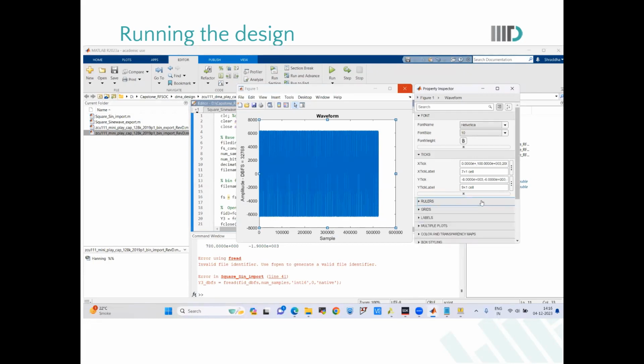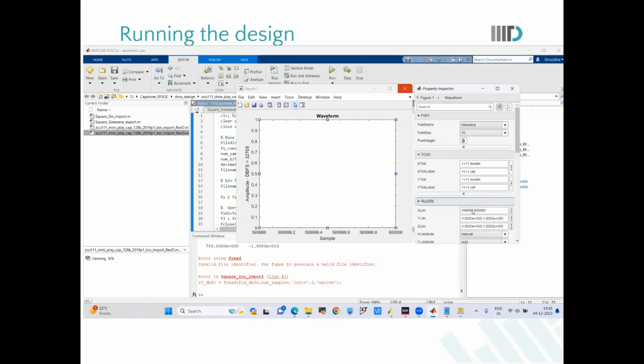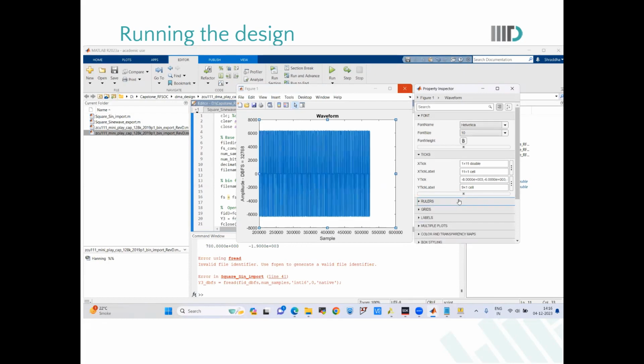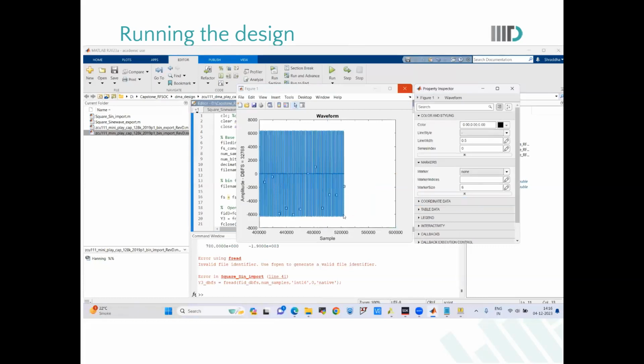Basically, you can see the main advantage of using DMA is that you can capture a large amount of samples at ADC in. Sample size can be changed up to the available memory size. Right now we have a PS DDR memory size of 4 GB. So whatever available memory size we have, we can capture that much data using the DMA-based design. So here you can see we captured the 512 kilo samples of data. Through this you can verify it.